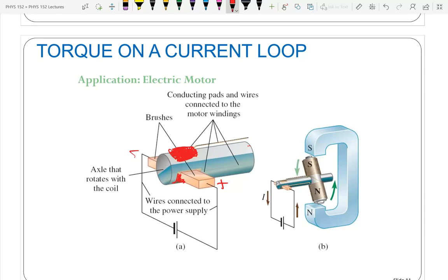With a DC motor, you don't have a way to control the frequency. What you can do is control the current. More current's going to give you more torque. It'll go faster before it reaches its final speed. So with a DC motor, the higher the current, the higher the maximum speed. With an AC motor, assuming you have enough current, the frequency will be the frequency that you're putting in.